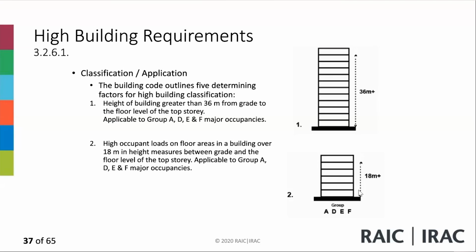So you need to take a look at the exit capacity on a discharge story of exit discharge to be able to accommodate all the people from the floors above. And there is a comparison, and there's an equation that you can use, and we'll show it to you.